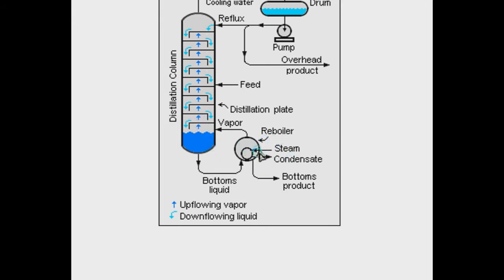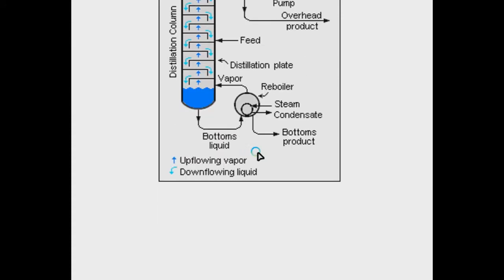It is also based on two types. Reboiler can be of the kettle type, or it can be a thermosiphon. The design of a thermosiphon is mostly a vertical shell with tubes inside it, most similar to the shell and tube type heat exchanger. While the kettle type reboiler is different, and there is a composition difference, so you can have bottom product and the vapor having different composition, while in thermosiphon both have the same composition.